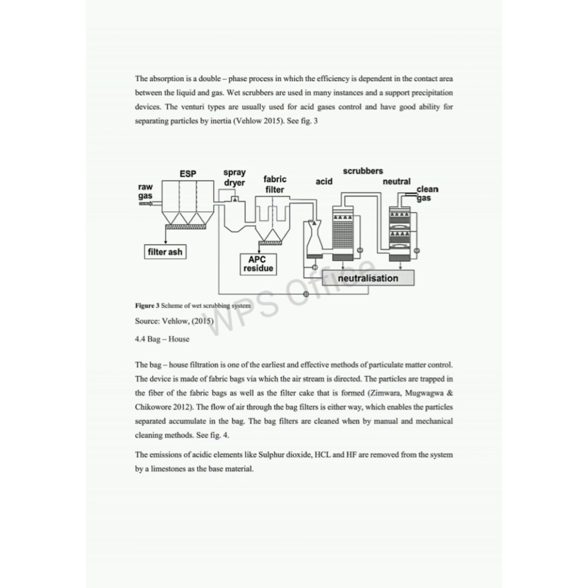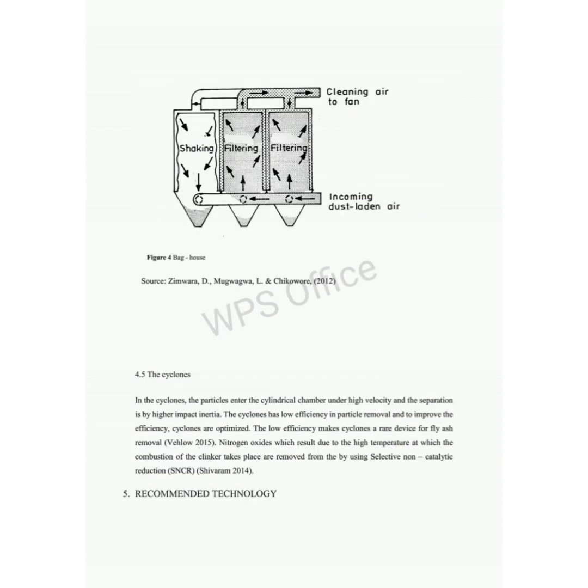The emission of the acidic elements like sulfur dioxide, HCl, HF are removed from the system by limestone as the base material. The cyclone. In the cyclones, the gas enters the cylindrical chamber under high velocity, and the separation is by the higher impact inertia.